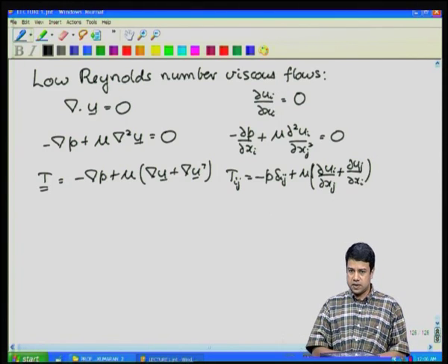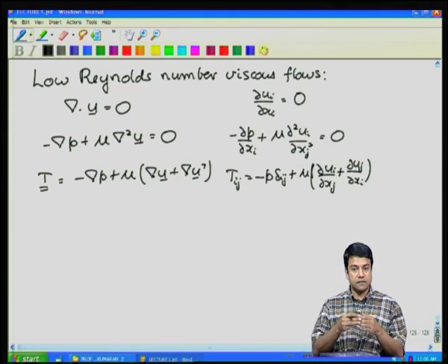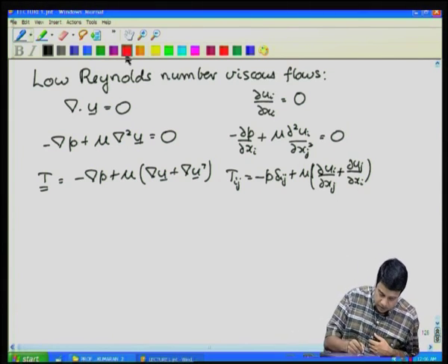These equations are quasi steady, no dependence on time in the equations themselves. So, therefore, you are not solving a partial derivative in time, where a difference in the value of some quantity, in this case the velocity, between two different time instants comes in. That means that at a given instant in time, the velocity field is completely specified by the velocities or stresses at the boundaries at that instant in time. Okay. So, for that reason it is called quasi steady.